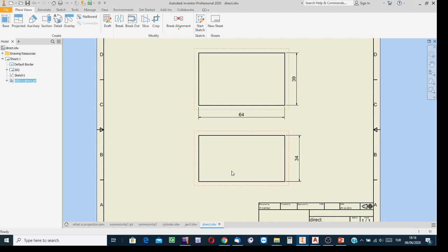Create the model of the object. But in which size? Well, the answer comes from the learning outcome on the dimensioning format, and also orthographic projection. Between the front and the top, we have the x-axis, and delta x is the width of the object. Yes, 64 is the width. Okay? And 39 is the height. 34 is the depth of the object.